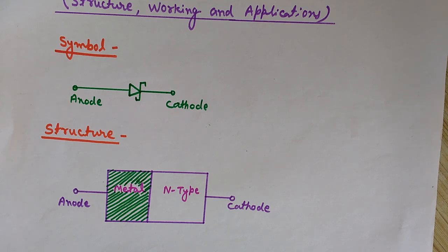It finds applications in switching power supplies, up to nearly 20 gigahertz, and also in sensitive communications receivers like in radars because of its low noise figure. And we can also use these Schottky diodes in computer gating and in clipping and clamping circuits.